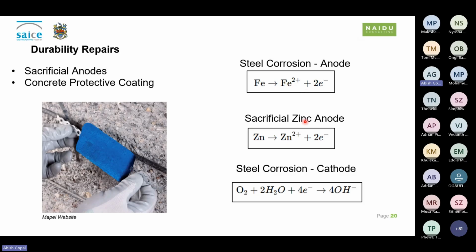Now, this concrete system itself acts as a galvanic cell, which is essentially a migration of ions, which initiates that. Therefore, that migration of ions can lead to the breakdown of the anode, which in our case is our reinforcement steel. Now, ways to mitigate this, one may ask, how can we reduce this effect? Well, the answer is cathodic protection, but specifically in the form of sacrificial anodes.